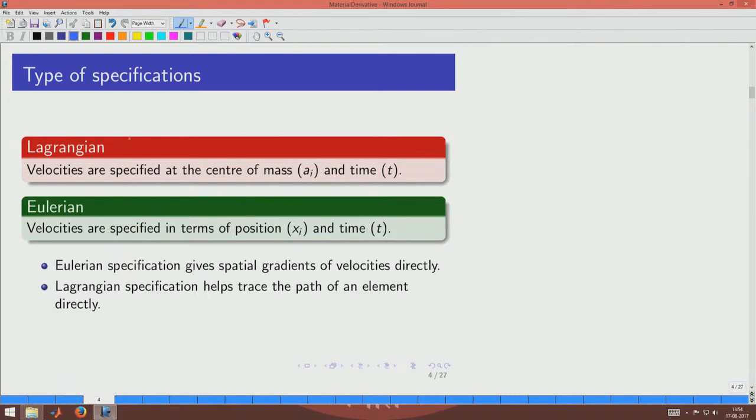So, the Lagrangian is what we say the car driver, how the parameters are being seen as defined at the location where the car is in a traffic flow, and Eulerian is by the same example how the traffic cop would see the various parameters like the acceleration or speed of a vehicle, and he would look at these as a function of the location of space.